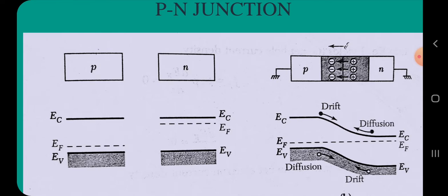The lower illustration in the figure shows that the whole diffusion current flows from left to right, whereas the whole drift current due to the electric field flows from right to left. The electron diffusion current also flows from left to right, whereas the electron drift current flows in the opposite direction. We note that because of the negative charge, the electrons diffuse from right to left, opposite the direction of the electron current. Now we discuss what are the equilibrium Fermi levels.